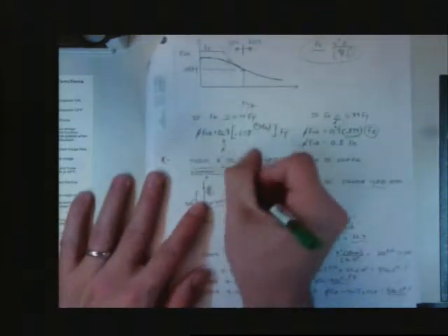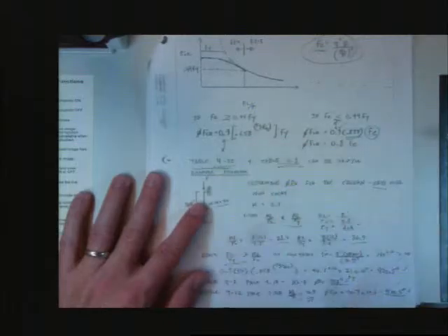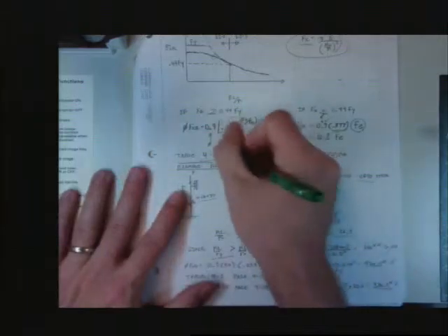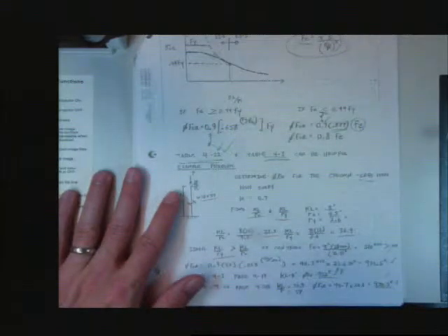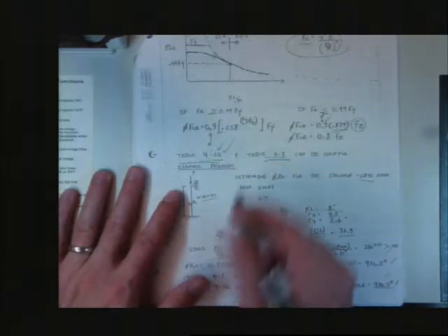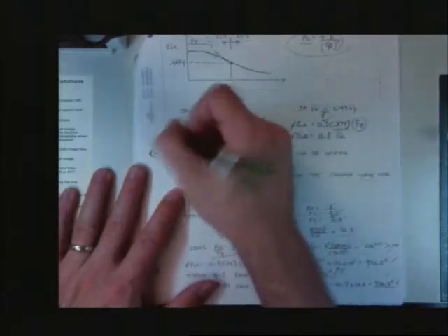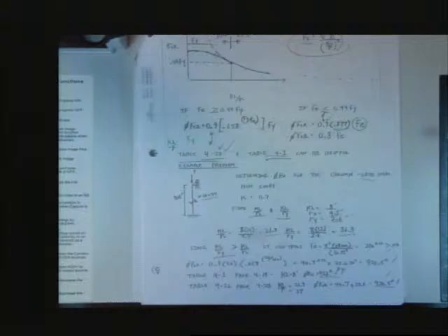Oh, yeah. Before I introduce the equations, there's a table 4-22 and a table 4-1. If you've never used those tables before, you should look them up. They're really useful, extremely helpful. Table 4-22 is the one that people like to use because the only thing you need to know is KL over r and Fy. That's all you need.